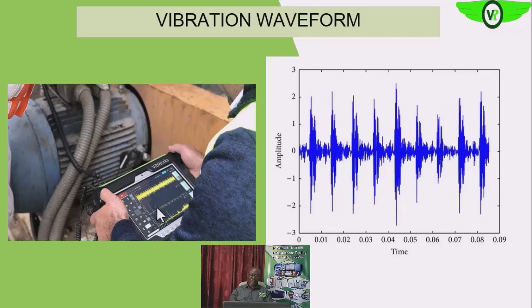So if you look at the analyzer, this is the spectrum underneath the waveform. With this, you'll be able to know what is actually causing that increase in vibration, or what is causing this impact that you are seeing on this waveform. So with experience and the rest, you'll be able to ascertain the causes.